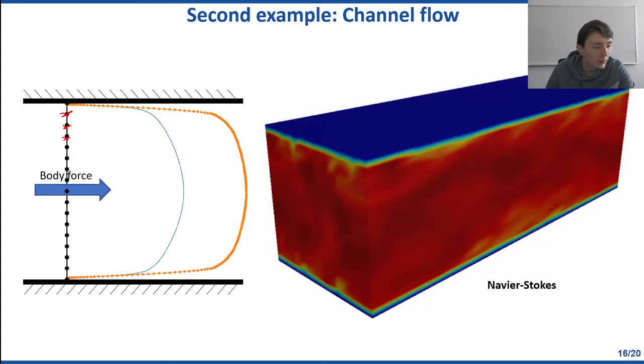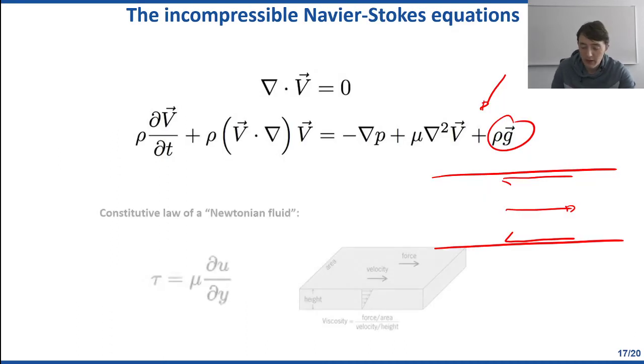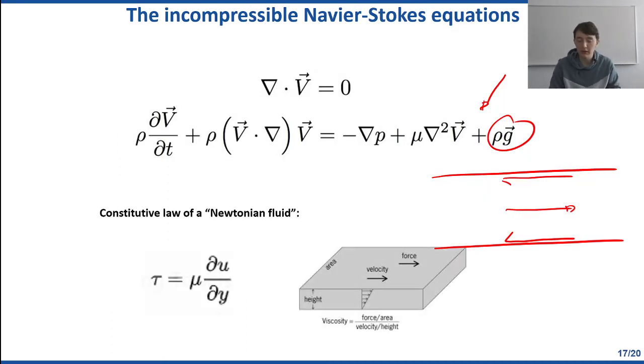Now clearly, by doing what we're doing here, we have this complete overprediction of our mean flow, meaning that we have a much higher flow at the point where we have this balance between the shear stress pushing the flow back and a pressure differential pushing the flow forward.